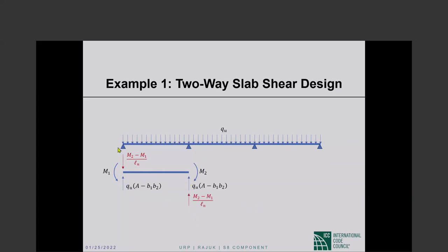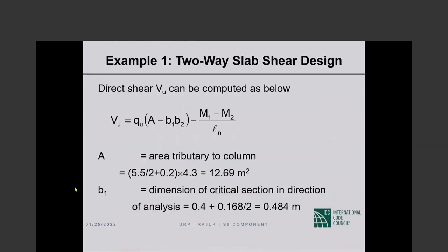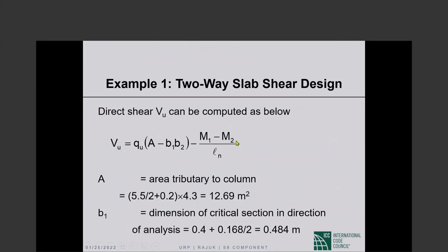Okay, we are considering the left support. So the shear at the left support is not just that, but also the shear caused by the two end moments. And that shear due to the end moments takes away from the direct shear. Okay? So this is what we wrote here. And that part is important. Sometimes people do not bother about the moment, but you should. This is the right way to do it.